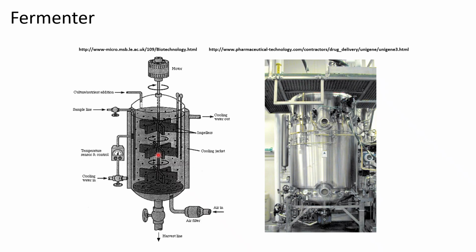In fermentation, as these microorganisms, typically yeast, convert the sugar, the glucose, into ethanol, they also produce a little bit of heat. So often you'll have a cooling jacket around the fermenter in order to maintain the temperature so it doesn't heat up too much, which will have an adverse effect on the yeast. They can only operate effectively within a fairly narrow temperature range.